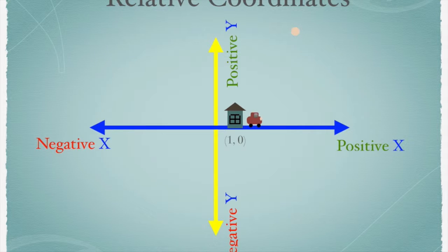But let's say that you want to go out for some ice cream. Okay, and the ice cream place is this way. It lives at absolute coordinate 10, 10. Just kind of like you would punch into your GPS the address, that we're going to kind of drive ourselves there. So you would need to tell the program, AutoCAD, how you are changing in the x direction first and then the y direction. So we need to go 9 units to the right, which ends up being 9 on the x. And then we need to go 10 units up, which would be 10 on the y.